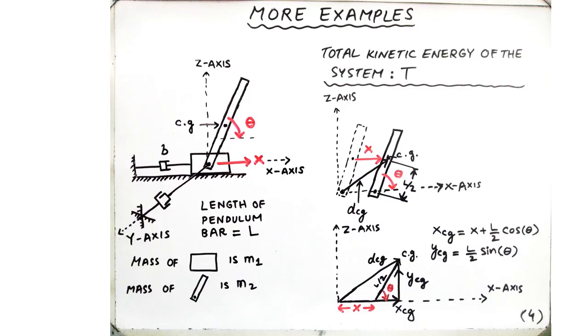If we first calculate the translational component, we require the entire pendulum bar mass to be treated as a point mass, and the best location for such treatment will be the center of its mass or the center of gravity. In some sense, we wish to shrink the entire pendulum bar to a point mass at its center of gravity and associate a displacement variable with reference to the global axis.